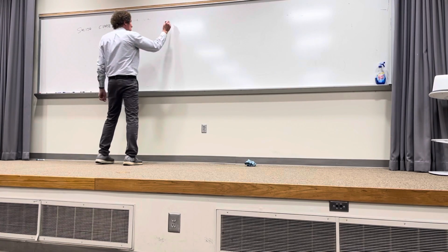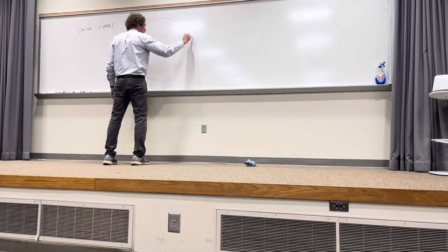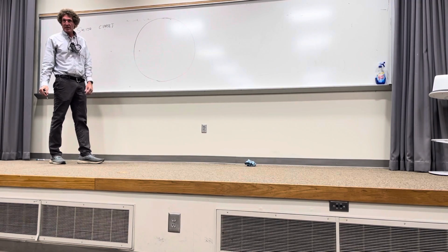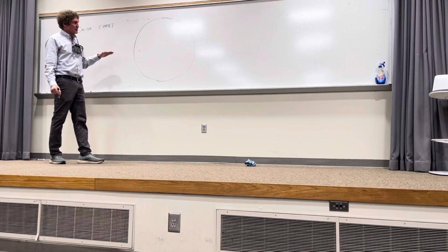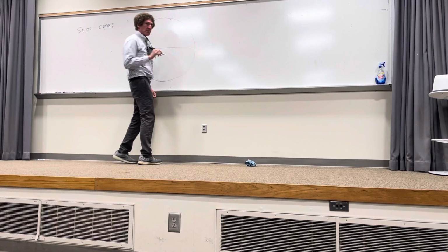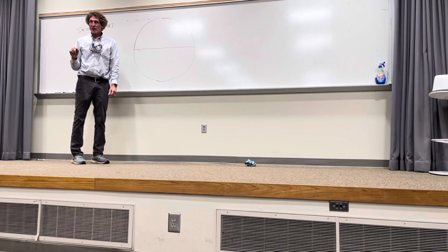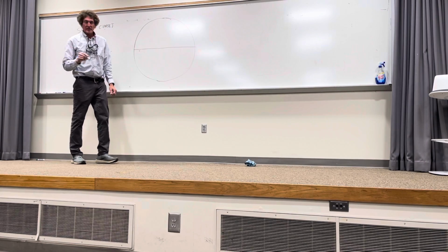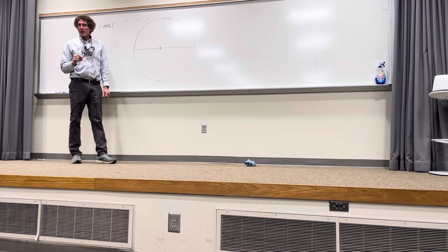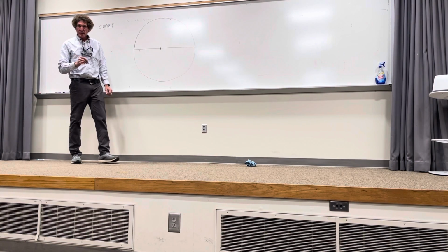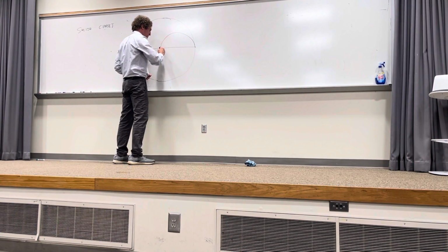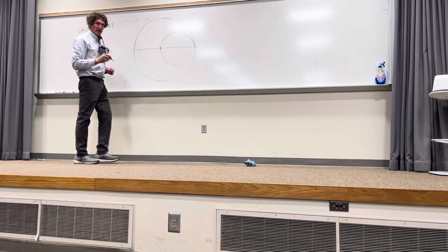So a Smith chart starts off looking like a giant circle, like so. And then after that, the next thing I always do is say, put in the equator. So just right across here, draw a line. Then find the center of this. Then put in another circle that snugly fits between these 2 points, as such. You got that?